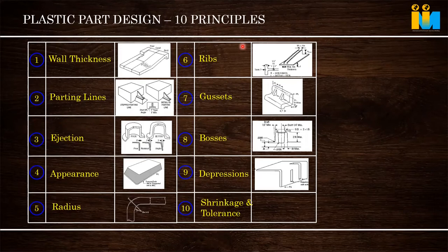If you're taking the best material, what thickness can I go? See, plastic cannot be molded at much higher thickness because the internal area will not cool. If it has much better conductivity, you can go slightly to 6 mm, 7 mm, 8 mm. But then in the mold, you have to put that much amount of cooling line. Sometimes you have to put it into water to cool. It's better to have thickness from 2 to 4 to 5 mm. That is the best for all the raw materials, not beyond that.